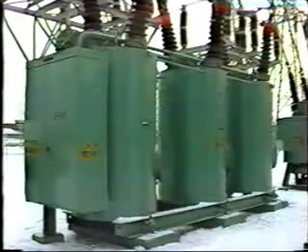At high voltage, say 345 kV, it takes about 21 cycles for the air gap at the fault to deionize. If we reclose the breaker too soon, the fault arc would immediately restrike. To prevent this occurrence, a time delay between opening and closing is usually built into the breaker by the manufacturer.